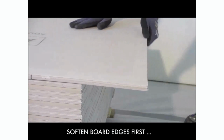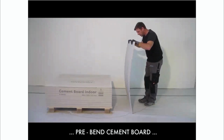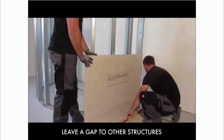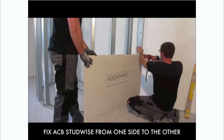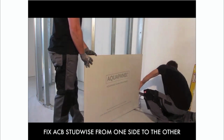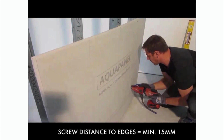Before you apply the board, you have to pre-bend the board. Loosen and soften the edges first, pre-bend the board, and shake it loose. This already makes it able to curve. Then you start to drill it onto the stud system. You don't require any pre-drilling, so drill it immediately onto the framing, and as you go along, gently bend it according to the curve of the structure.